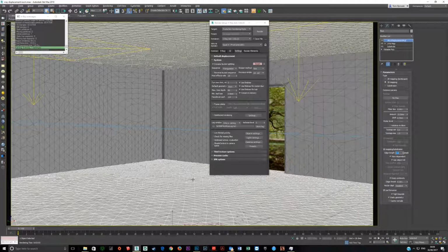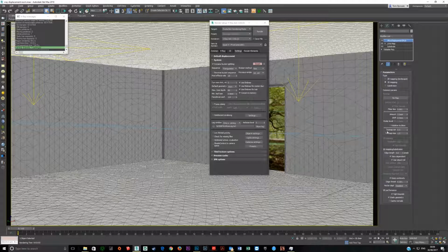These are really the tricks and tips if you're going to be using displacement. If you've got V-Ray, use V-Ray Displacement Modifier. I just leave it on 3D mapping. Set in your amount. If you're going to shift it back, let's say if I've got a flat brick wall, then I'll absolutely shift it back. I'll have the bricks coming out 5 mil, and then the normal operating procedure is you do half. Sorry, you do half minus 2.5. And that shifts the wall back minus 2.5 mil before it starts to displace. In this case, I'm leaving it at 0.